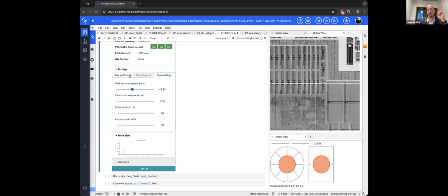Another question is about timing: how long should I activate the pulse? How long will it last? And that again will depend on what you are targeting. Are you targeting a single clock cycle? So you know the frequency, you can do the division by yourself and count the amount of time this round will last, and you will just set the value here accordingly, okay?